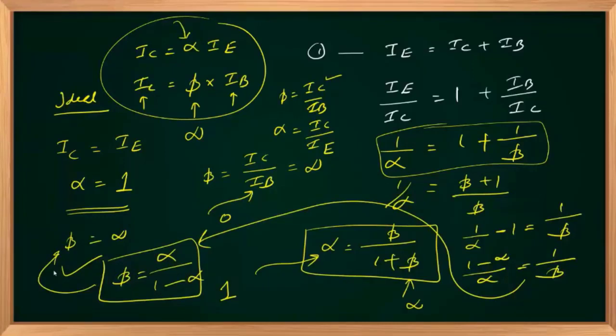Right? Clear? And why are we reverse biasing the base collector region? To make the collector current proportional to the applied base emitter voltage, so that the electrons emitted from the emitter region are collected by the collector. The base collector junction should pass all the electrons emitted from the emitter region, and the emitted electrons are minority carriers in the base region. To cross these minority carriers, we should reverse bias the base collector junction. Right? Clear? Any doubts? Okay.